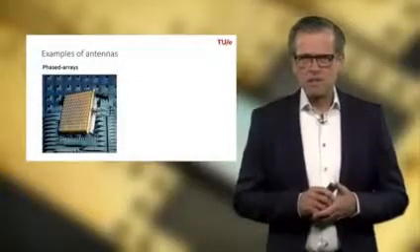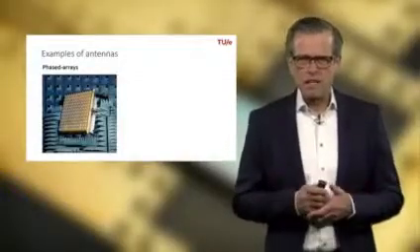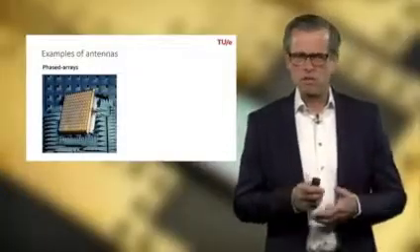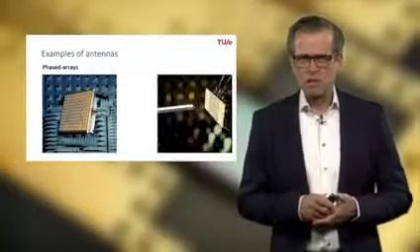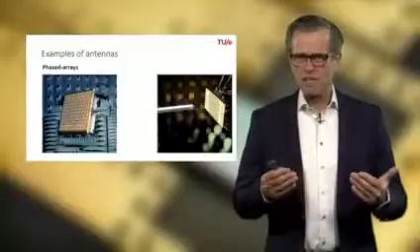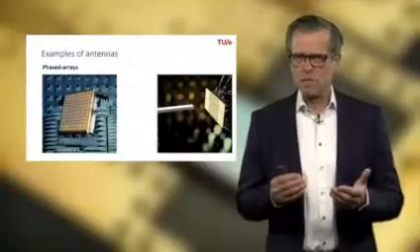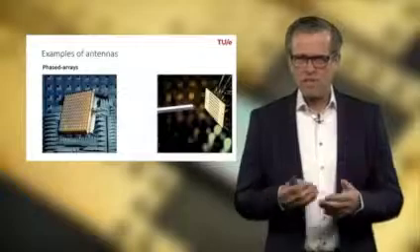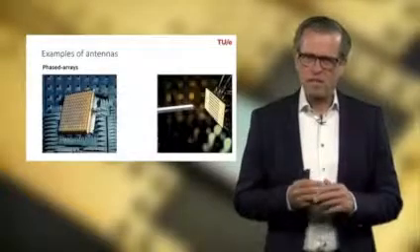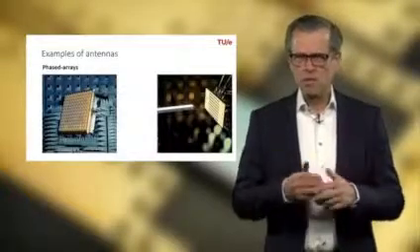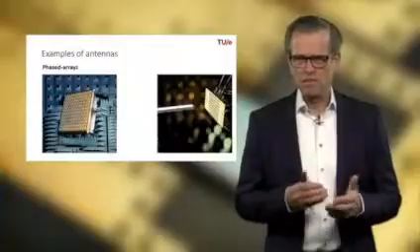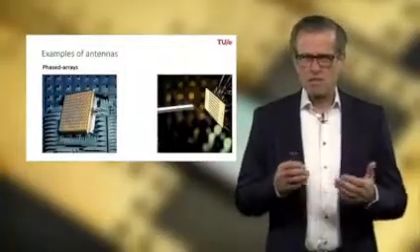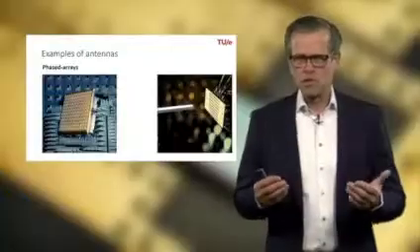Now, traditionally phased arrays are expensive, power hungry, and are used in professional applications like for radar or radio astronomy. But we see now a trend towards the application of phased arrays for wireless communication. And with the introduction of 5G, especially 5G operating at higher frequencies, at millimeter wave frequencies, at Ka band, that's about 30 gigahertz, we see that phased array technology is coming into the commercial applications.